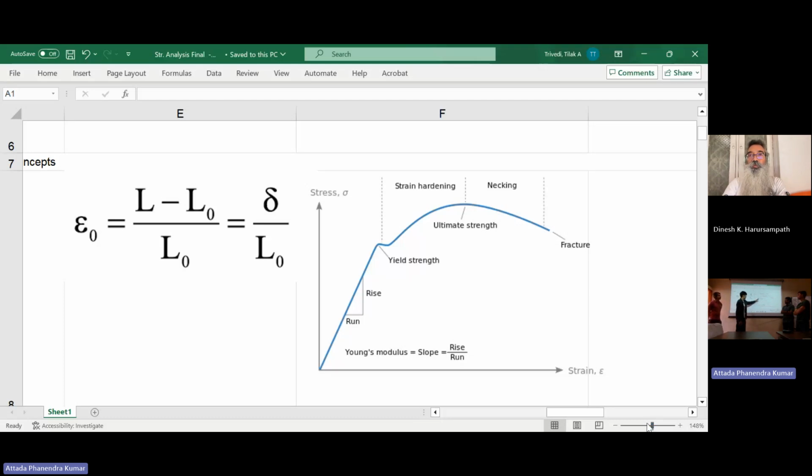We start out with this elongation period here, strain hardening, and then we have necking, which we've done a lot of experimentation in, like 2610 or 3610, where a dog bone shaped beam experiences necking, and then fracture, which is the point where the plastic deformation or the plastic region ends, and then it cracks, right?